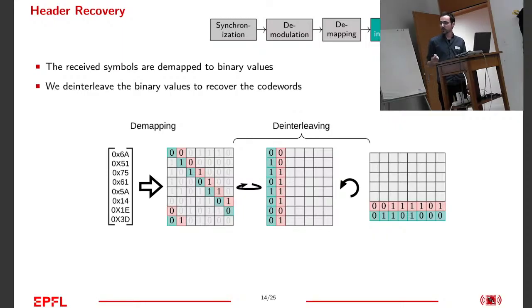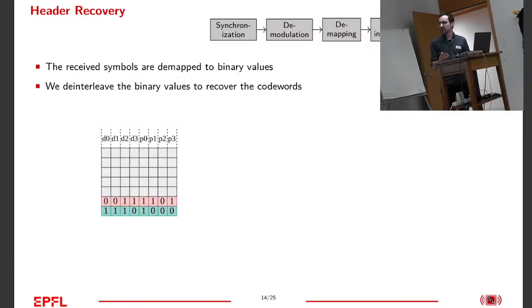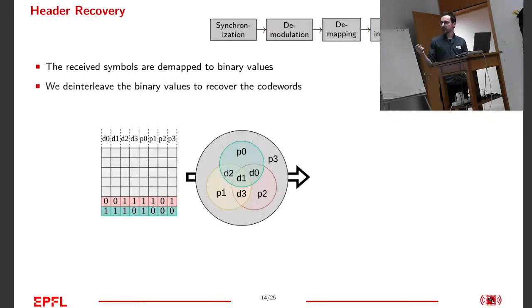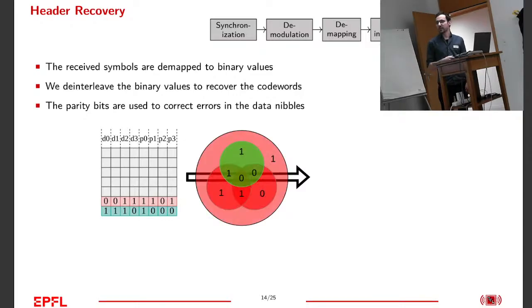So what LoRa uses is the Hamming code, so you can represent it with a Venn diagram like that. So you get parity bit 0, data bit 0, so you have 8 values that correspond to the 8 positions in one row. If you fill the 1s and 0s that you receive inside, and you do an XOR operation for each circle, so you just sum everything and do a modulo. If that gives you a 1, that means there is a problem, a 0 means it's all fine. And in that example, by luck, there is one error, so it's good to demonstrate.